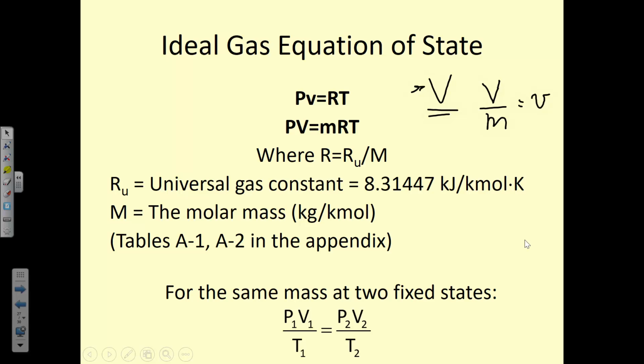Ideal gases, right? So don't try to use it on a problem with water or R134A or anything else that's not an ideal gas, unless the purpose of it is to show you how wrong it would be to use the ideal gas equation compared to looking it up in a property table or whatever it might be.